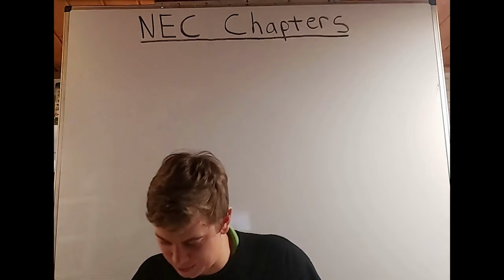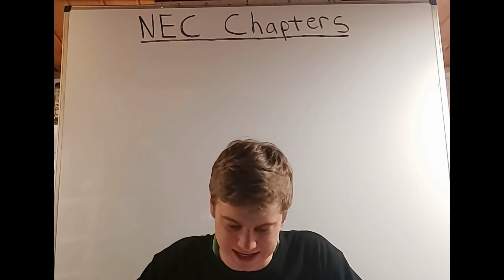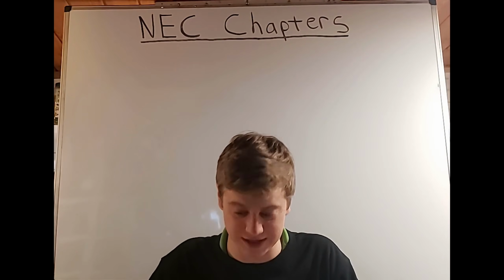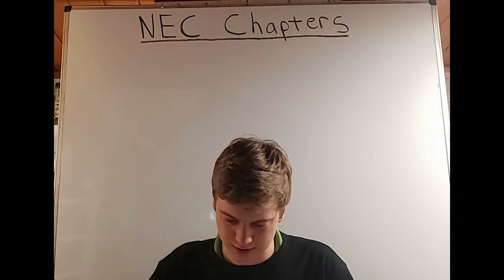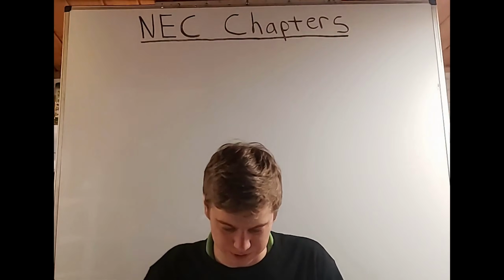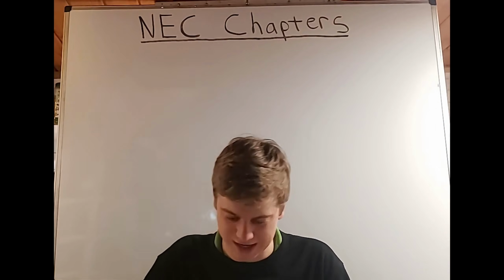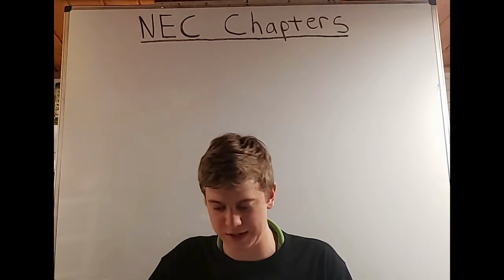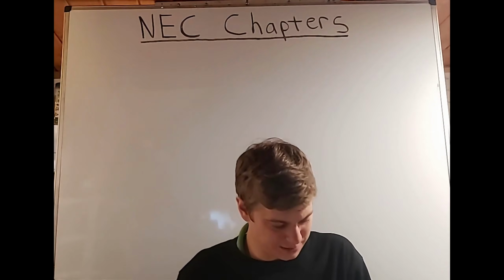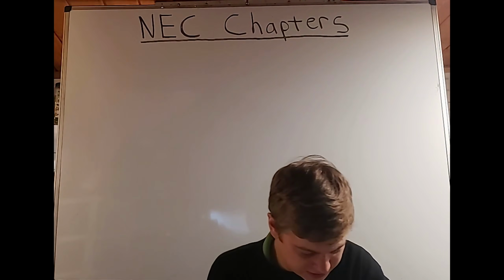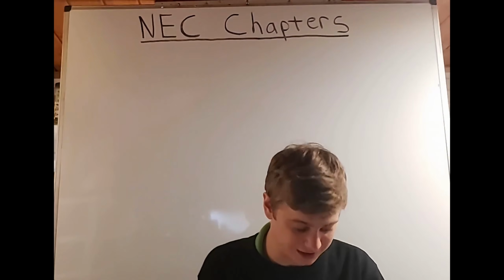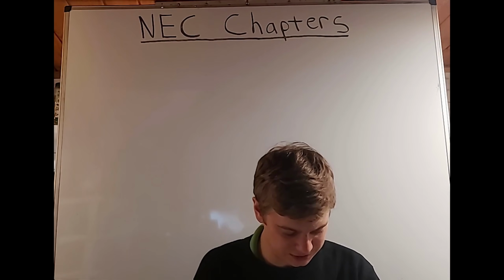Okay, we have table 310.15(B)(1). This is the ambient temperature correction factors based on 30 degrees Celsius, which is 86 degrees Fahrenheit. Okay, and you're going to want to highlight the 90-degree column there. We see table 310.15(B)(2), ambient temperature correction factors based on 40 degrees Celsius, which is 104 degrees Fahrenheit. Okay, moving on, we have table 310.15(C)(1), which is the adjustment factors for more than 3 current carrying conductors. And you see you have your percentage, your adjustment factor.